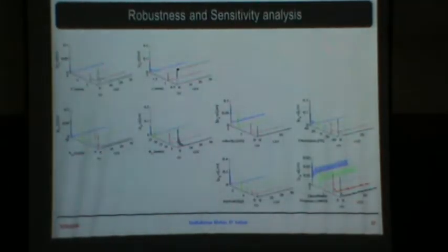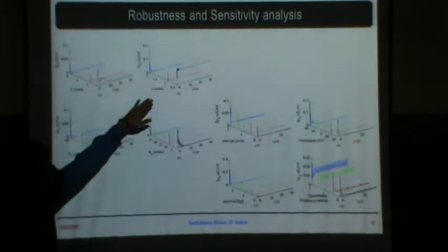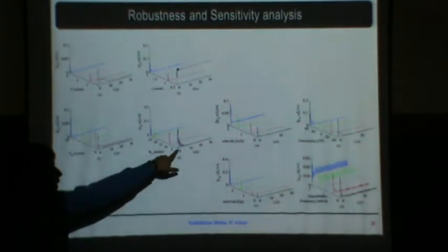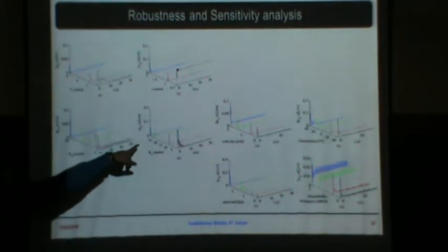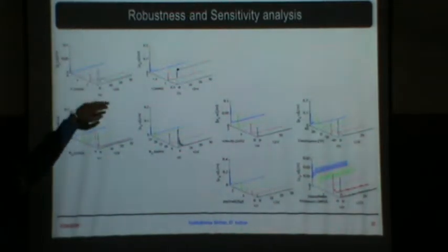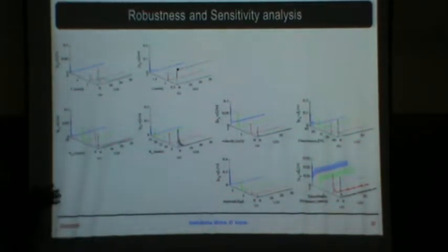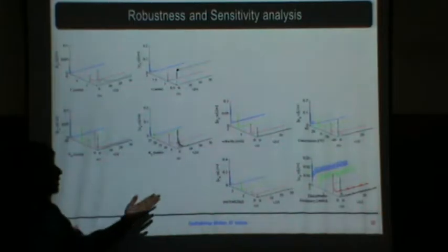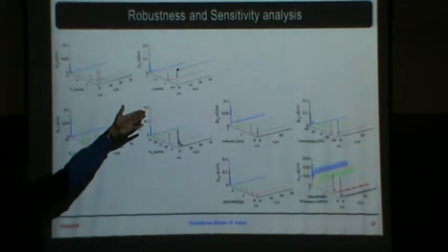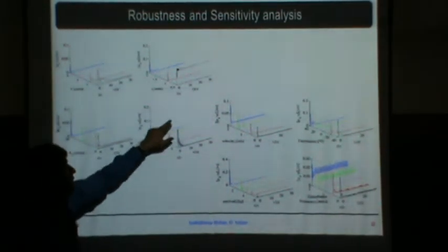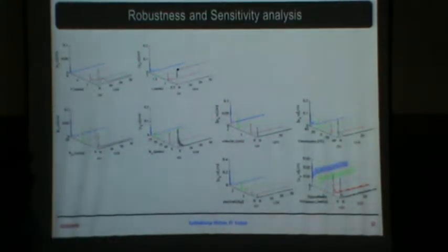In order to understand the robustness of the control, we have taken the control gains random, like the lambda, gamma value, Kc, K0 and all, in order to verify whether the sensitivity is there or not. We vary them from 0 to 26, or probably here 30, here 0 to 50, then 0 to 6, and 0.5 to 2. We vary all the values and see that yes, there is a sensitivity in Kc, because when the control gain is 0, only the feedback linearization remains, and it will not help. That's why you can see that it is going more than 10 centimeter in the initial experiment.